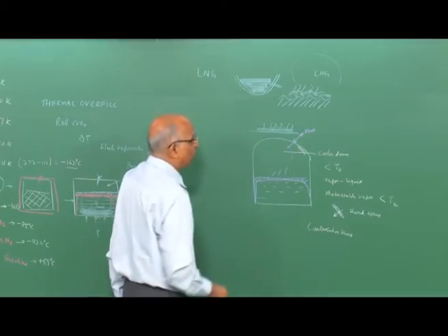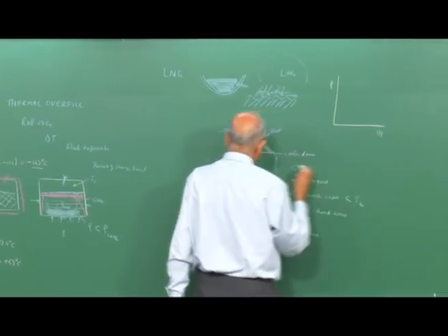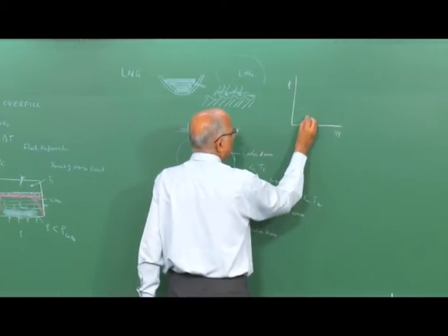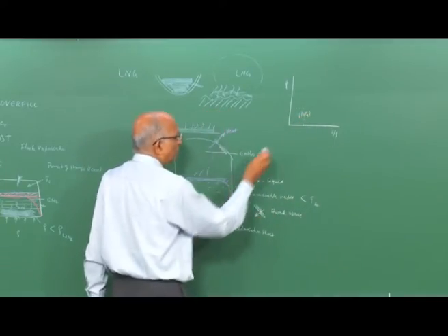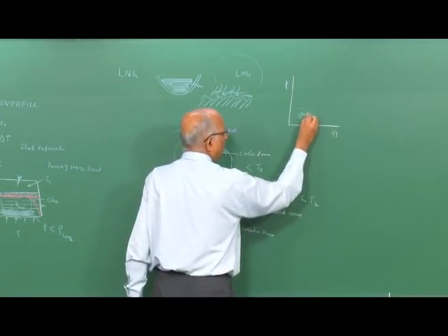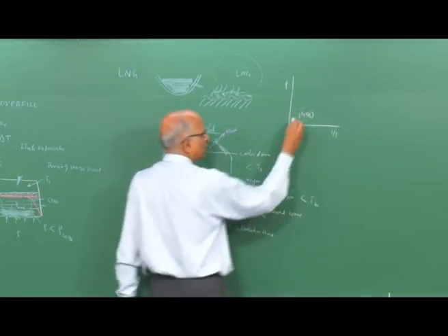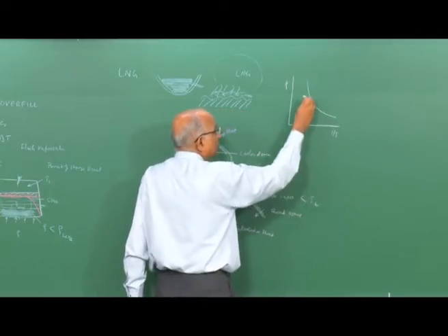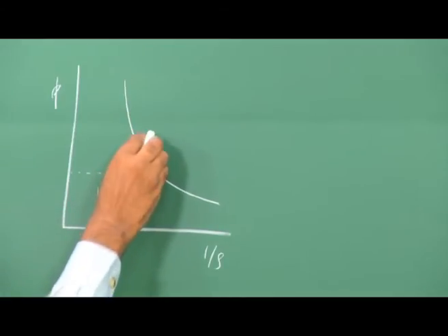We can readily show this on our diagram, namely I have pressure versus 1 over rho. The initial conditions corresponding to the cool down conditions can be shown by the initial conditions P0 and rho 0, or let us say 1 over rho 0, because my scale is 1 over rho here, so I have P0 and 1 over rho 0. And since some heat is associated with condensation, I have something equivalent to a condensation process over here, which is, let us say, metastable, and when it condenses, I have heat which is getting generated.